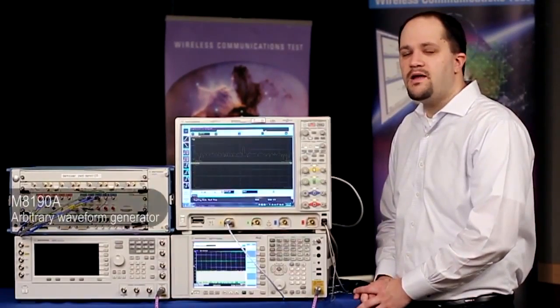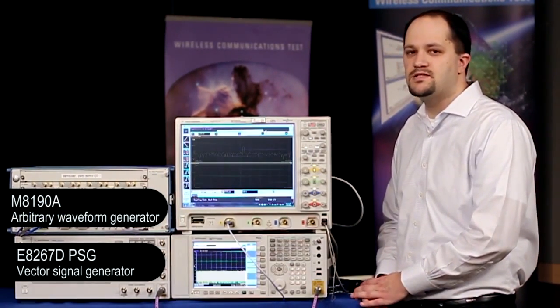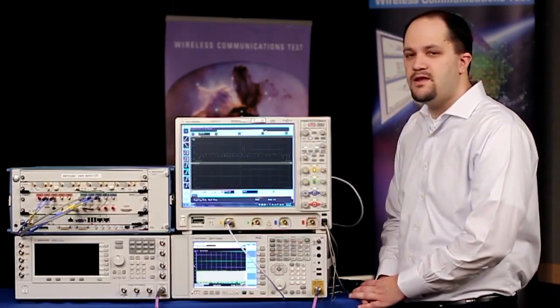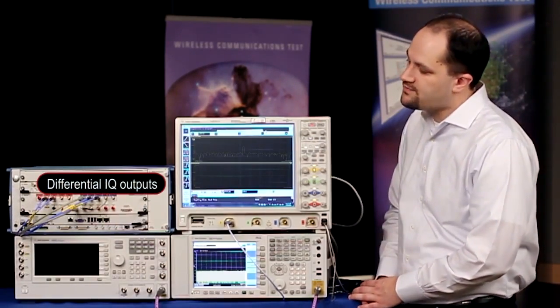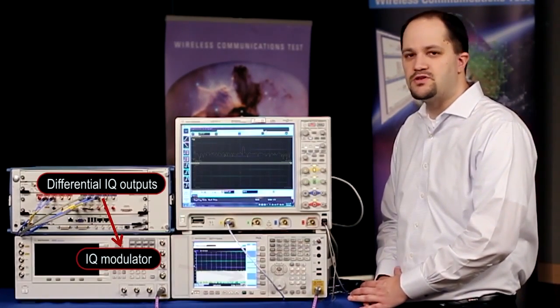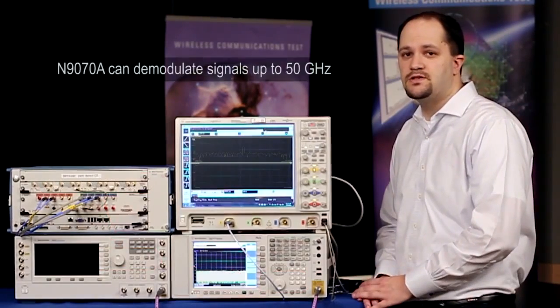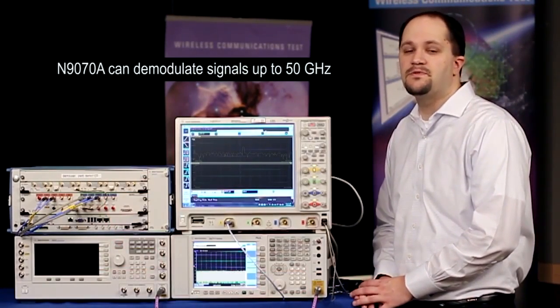Also, we have a wideband arbitrary waveform generator and a vector PSG to generate these wideband signals. The M8190's differential IQ outputs are connected to the vector PSG's IQ modulator, which then upconverts a signal up to 44 GHz. Our analysis solution can demodulate or analyze signals up to 50 GHz.